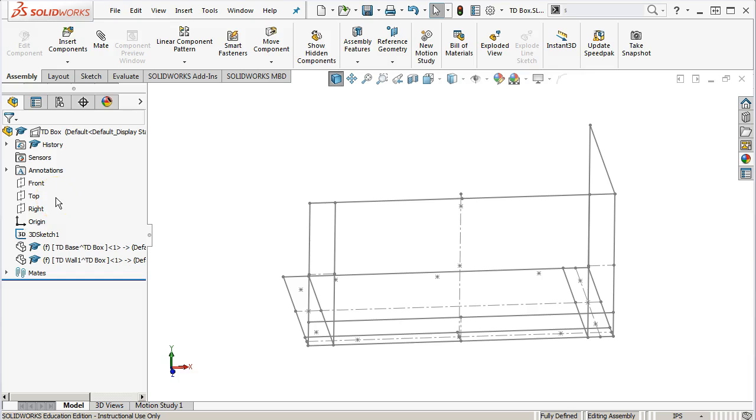And probably the other advantage is that there isn't a limitation on suppressing components at this level, or having to worry about the difference between hide and suppress. Do you hide the components so you won't reference them? Yeah. I really want all of the components that I'm inserting tied to this 3D sketch, not to each other. Wherever possible, I don't want this one tied to this one, tied to this one. There may be times where it becomes necessary, but it's going to be limited.